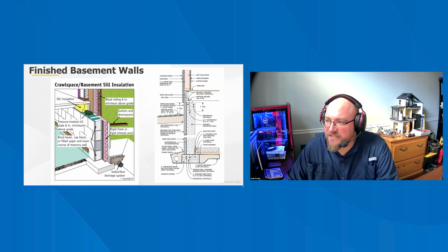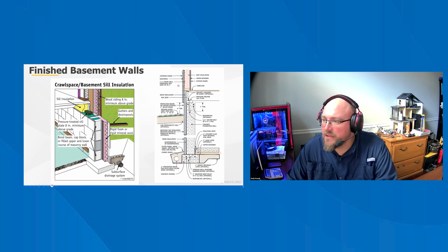This exterior insulation, or foam panels on the outside of the foundation, provides a moisture-tolerant insulation layer on the outside of the foundation wall. This insulation layer moderates the temperature of the inside wall surface and can also integrate with an exterior water or damp proofing. If this type of insulation is installed, it requires shifting the house structure outward such that the sill plate overlaps. You can see here, this little area, that the